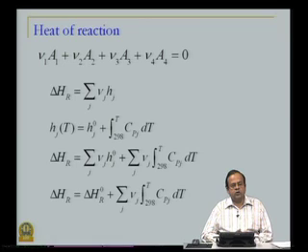Before we close our discussion on thermodynamics and chemical reactions, this you have seen before, but just a recap of how do we calculate the heat of reaction. We talked about heat of reaction either positive, that means an endothermic reaction, or negative as an exothermic reaction. Incidentally, steam cracking is an endothermic reaction, ammonia synthesis is an exothermic reaction. So, now you can consider what temperatures other conditions should be, but how do we calculate this heat of reaction?